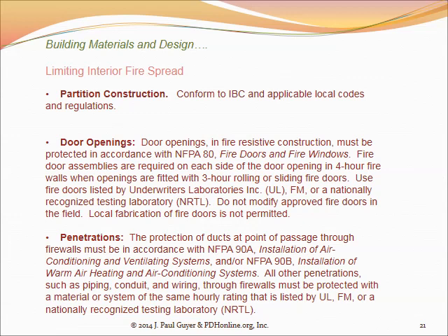That means the corridors, so that people can get out of the building in the event of a fire. And so the codes will say that your ordinary partition walls between offices can be of 1 hour fire-resistive construction, but the walls and ceiling in the corridor must be of 2 hour fire-resistive construction.